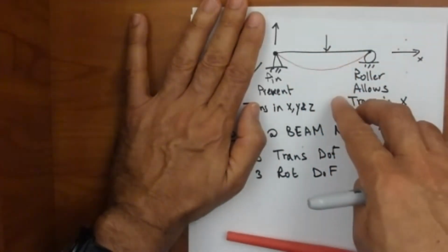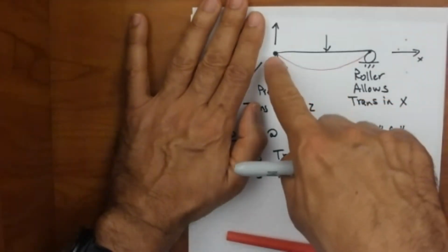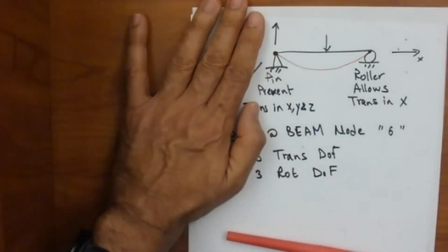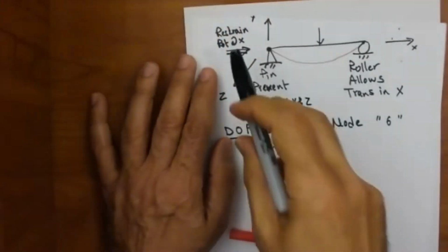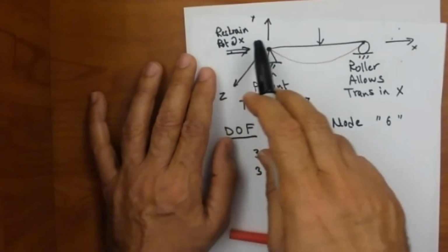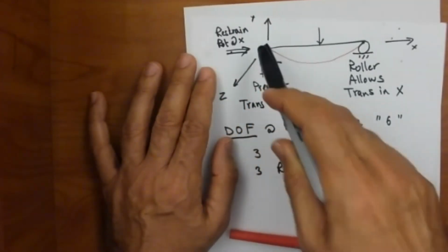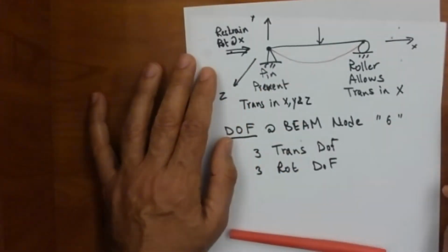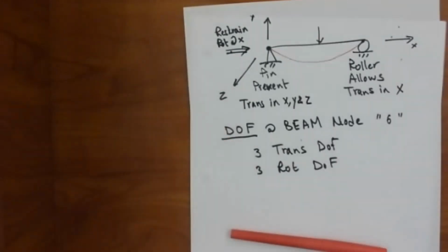So I can introduce a support, just to hold this from the outside by preventing this rotation about the x-axis. So I can add a restraint for the rotation about the x-axis at this end, and we need to do it so that numerically we get a solution. Okay, let's apply that in ANSYS Workbench.